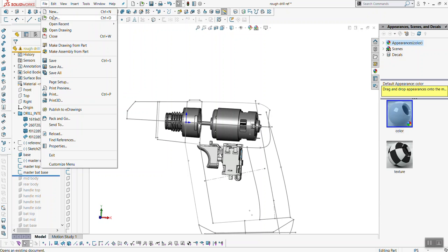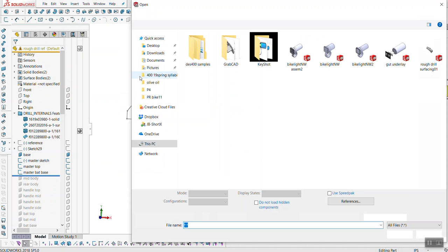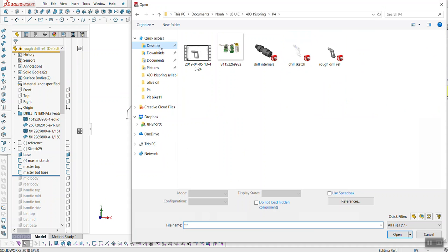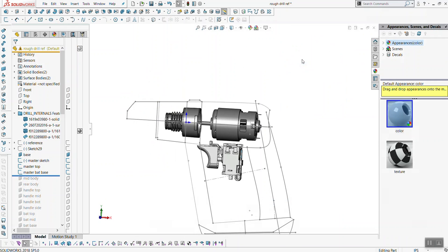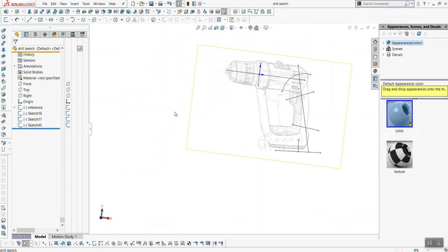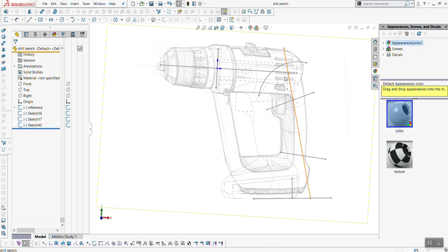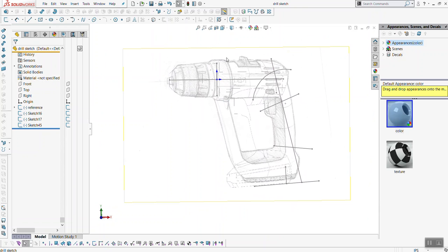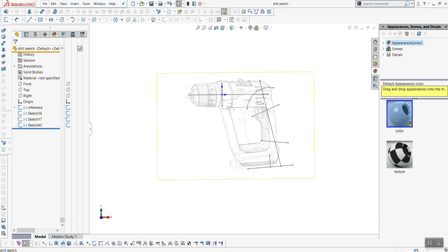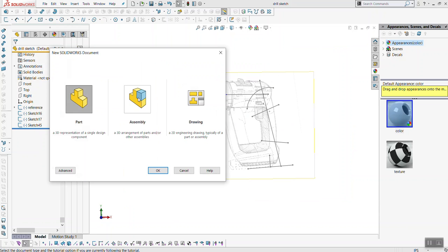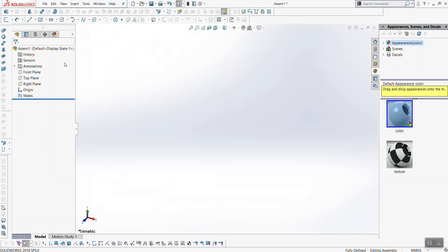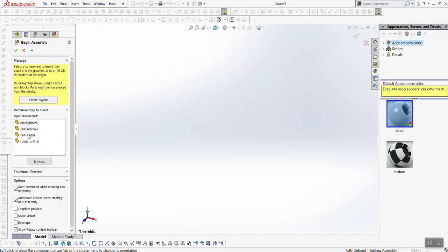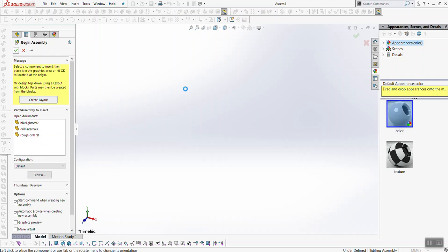So you may start a new file just like we did with the bottle project, where you might have your sketch imported into the file here. And then you might start, this is a very rough master, but you might start a master sketch with that. At that stage, what I would do is I would make an assembly. So I'd go File, New, Assembly, and insert your beginning part file.